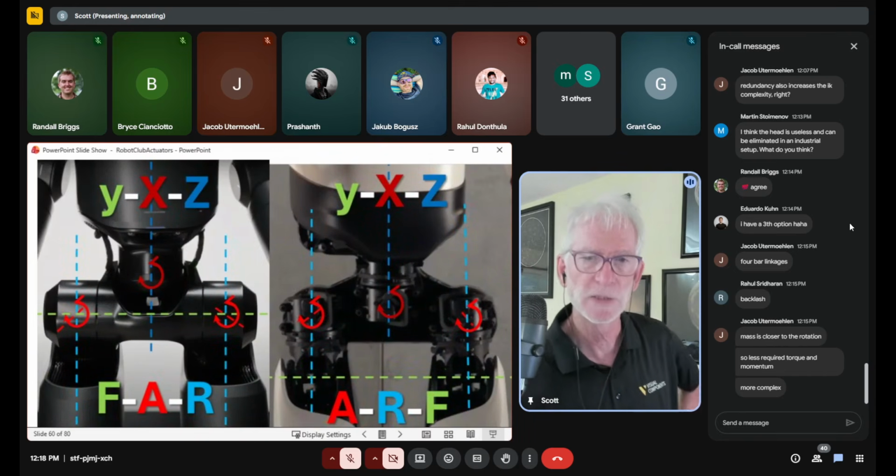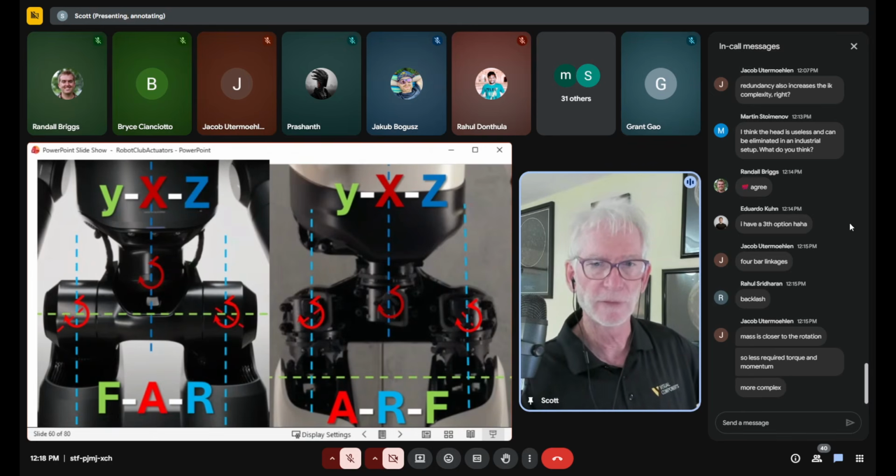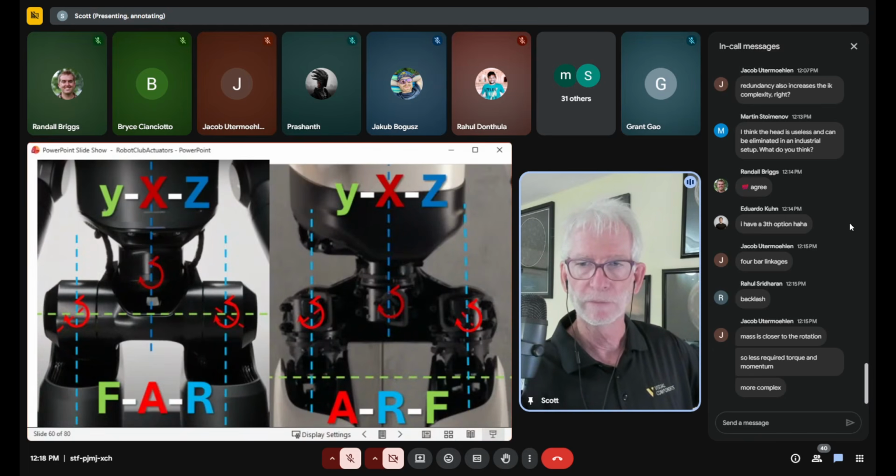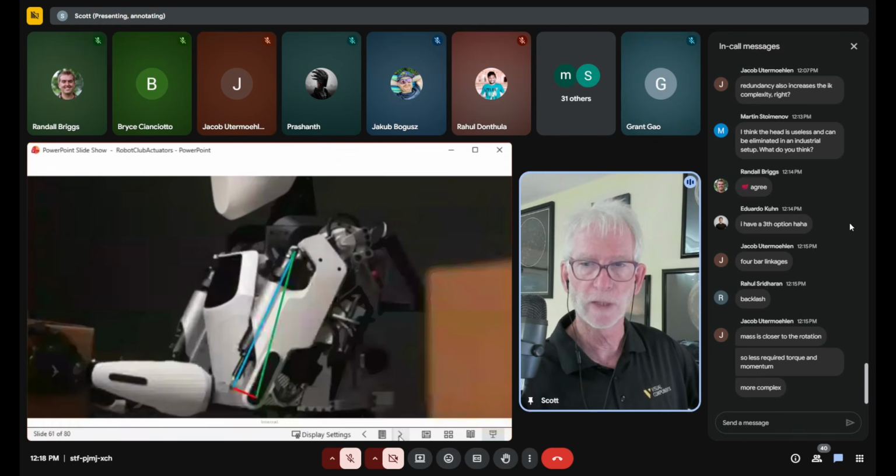Okay, so here's an example of trying to build my bot out of actuators at the joints. On the left, we can see Figure, and basically every single degree of freedom in here is the actuator itself, right where it needs to be. Optimus has a lot of them there, but the F that you see right there is using a remote actuation strategy where it ends up using a linear actuator. So in many cases, you can do a mix and match, but the more that you actually build them in there, the happier it will be for being able to do RL.